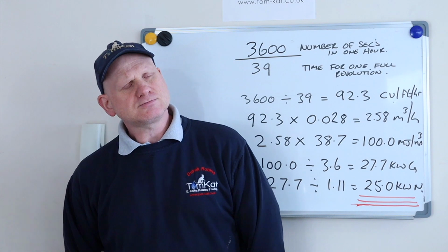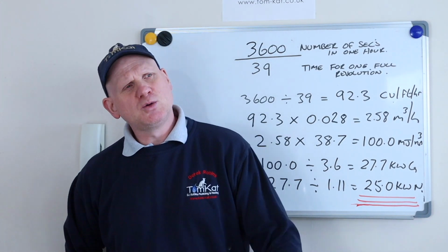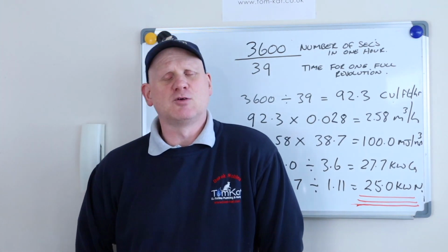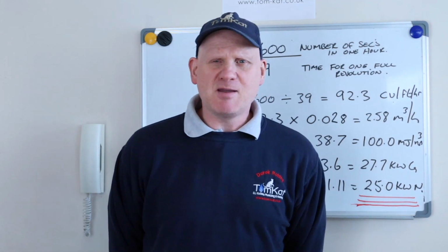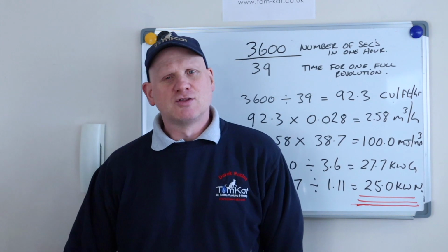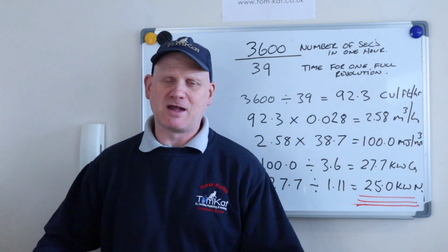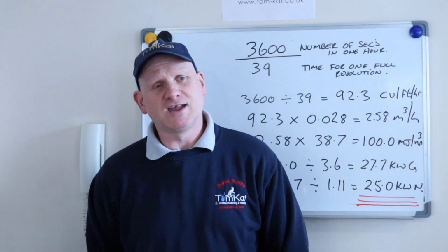Now, we just gas rated a combi boiler. According to the manufacturers, Ariston, for that boiler, it's a 24 kilowatt combi boiler. But we've just gas rated the input, not the output. The 24 kilowatts is the maximum output for that boiler. So depending on how efficient it is, will depend on what your gas rate is.